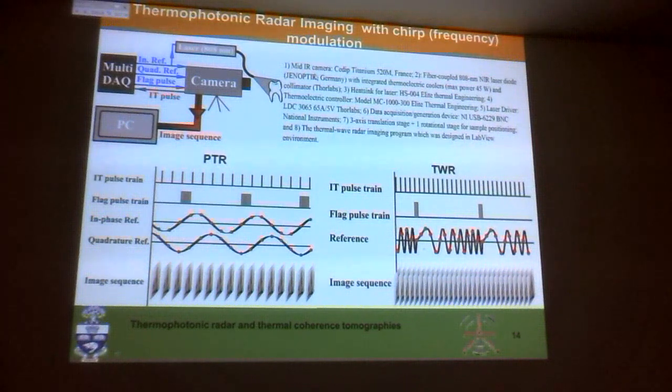If you're really looking at thin coatings on surfaces, then 1,000 hertz is difficult. So one of the ways that we overcome this, and we're not really working in that range yet, is to use some heterodyne schemes, which means that you have 2 frequencies going together, F1 and F2. Let's say I have 1,000 hertz and 1,010 hertz together. I mix the 2 fields just like a beat. You generate the beat wave. So I have the 1,000 and then the 10 hertz, F1 minus F2. So the camera locks onto the 10 hertz, which it is very comfortable with. What it does is take the amplitude of the high frequency end and bring it down to the low frequencies. So at 10 hertz, you get information about 1,000 hertz. That's one of the ways of doing that.